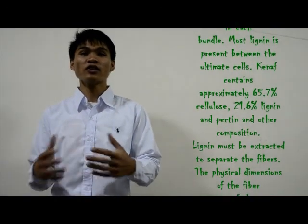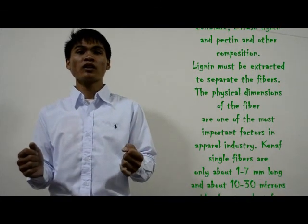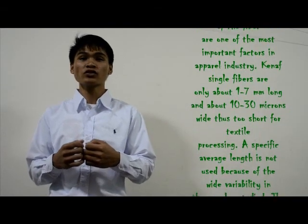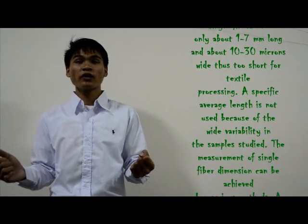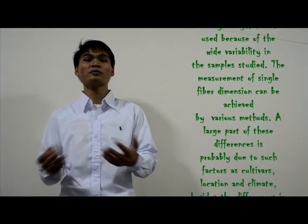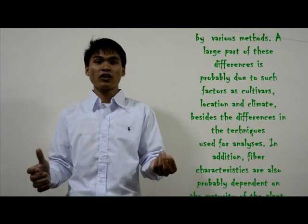The physical dimension of the fiber is one of the most important factors in the apparel industry. Kenaf single fibers are only about 1 to 7 mm long and about 10 to 30 microns wide, and thus too short for textile processing. A specific average length is not used because of the wide variability in each study. The measurement of single fiber dimension can be achieved by various methods. A large part of these differences is probably due to such factors as cultivar, location and climate.